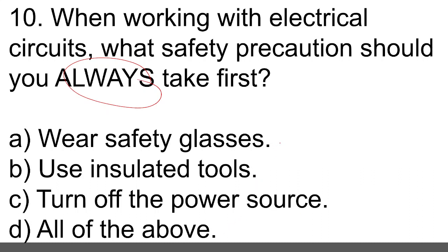So this can be answered by our mere observations or on a real life basis that in any electrical installation or maintenance, you have to wear safety glass, you have to use insulated tools, and first and foremost, you have to turn off the power source through tripping the main circuit breaker or manually tripping off the circuit or the main fuse. So therefore, our answer here is all of the above. Lahat yan ay kinakailangan nyo.